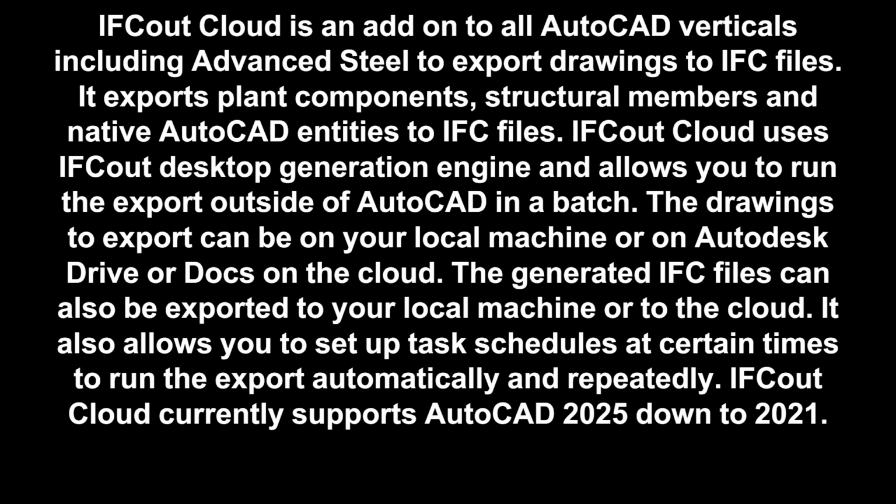IFCout Cloud uses the IFCout Desktop Generation Engine and allows you to run the export outside of AutoCAD in a batch. The drawings to export can be on your local machine or on Autodesk Drive or Docs on the cloud. The generated IFC files can also be exported to your local machine or to the cloud. It also allows you to set up task schedules at certain times to run the export automatically and repeatedly. IFCout Cloud currently supports AutoCAD 2025 down to 2021.